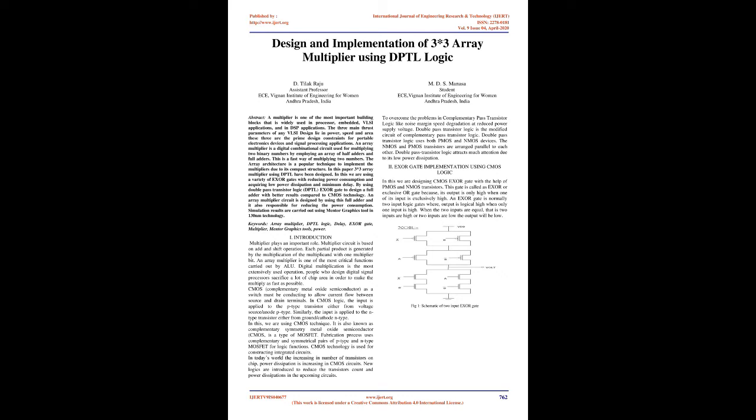The array architecture is a popular technique to implement the multipliers due to its compact structure. In this paper, a 3*3 array multiplier using DPTL has been designed. In this we are using a variety of EXOR gates, reducing power consumption and acquiring low power dissipation and minimum delay. By using double pass transistor logic, DPTL, EXOR gate to design a full adder with better results compared